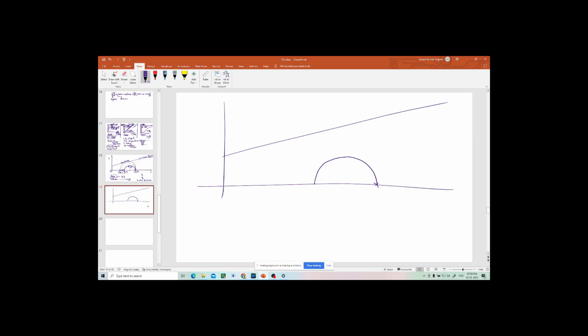But in case sigma h is greater than sigma v in the at rest condition. Now we will draw the Mohr circle for the active condition only. In the active condition, what will happen? Sigma h will decrease, sigma v will be constant, that we know anyway. So I'll keep this point constant. Now I should decrease this sigma h slowly. Let us see when it will fail.